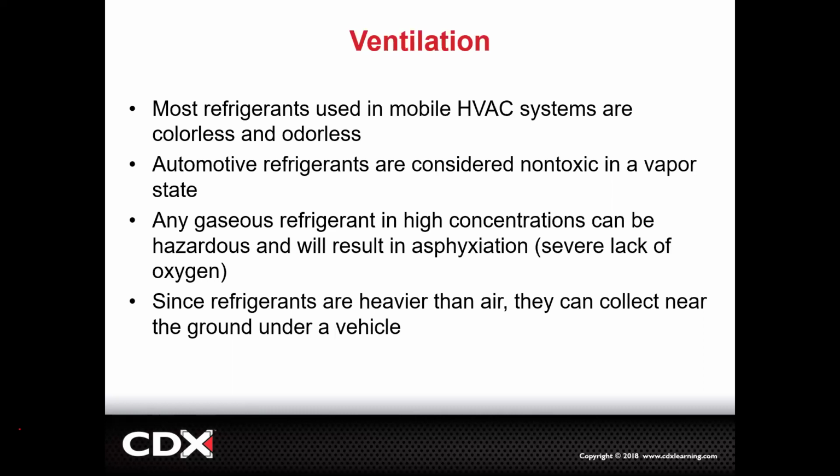Walk away, go outside. By the way, when we're really working on this, we're recovering this stuff. So if you're popping a line off and discharging it in your garage with all the doors shut, you may experience some of this. We're not going to do janky stuff like that. We're going to do it the right way. You're not going to even experience this, but you still need to be aware this will displace oxygen and cause you to get no oxygen to your brain, and you'll die from that if you do it. Okay. You won't die instantly, but if you were to stay in that environment, you would die.